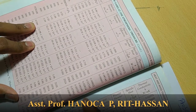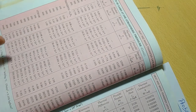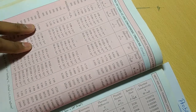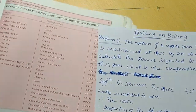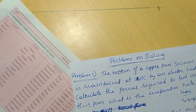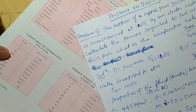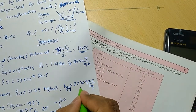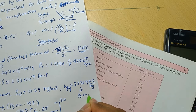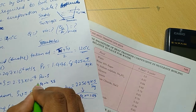If you take 0.598 or 0.59, that doesn't make much of a difference in the answer. You can take 0.598 also, no problem, but I have taken 0.590 kg per meter cube. Then hfg is also available in the data handbook, page number 144. In 144, hfg I have taken for 100 degrees centigrade as 2256.9, already explained. This is taken at page number 144, and this is taken from page number 38.